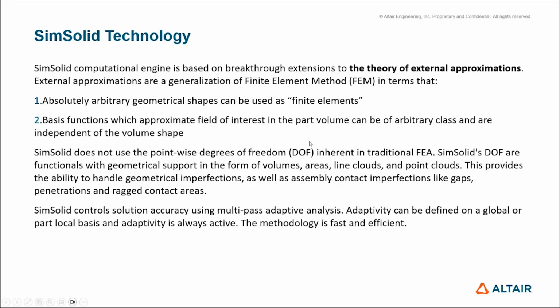That is how this method is developed. Basis functions which approximate the field of interest in the part volume can be of arbitrary class and are independent of the volume shape. Now what that means is holes, radii, certain stress concentrations are catered for with basis functions in the part volume as stated, independent of the shape. So the SimSolid solver is not worried about the shape. It's solving for the features within the volume, as I said, which is a finite element.